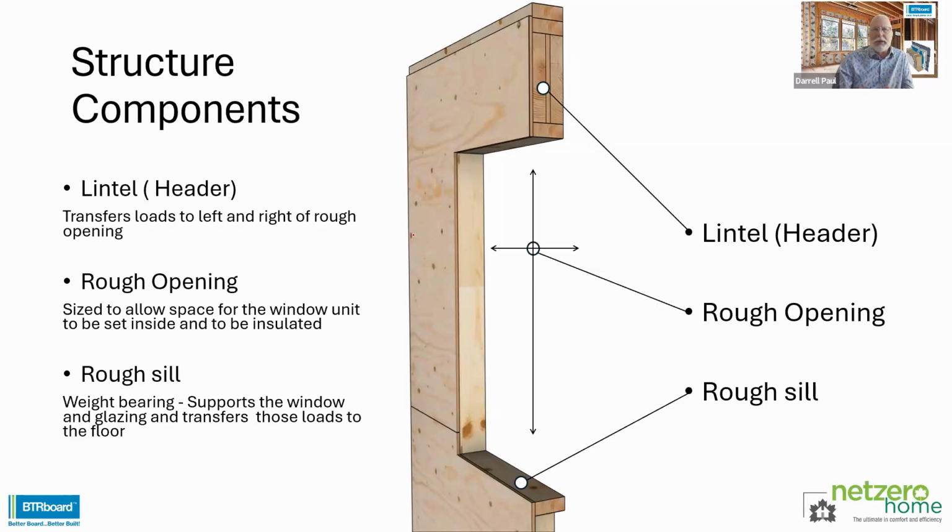All right, so there's some of the building science. We talked about the 4 control layers: water, air, vapor, and thermal. And we've talked a little bit about the first and second plane of protection, but let's go back to the rough opening. So here we're back to a rough opening. Maybe you've stripped the entire wall, maybe right down to the framing, or maybe this is what you need to envision as you're doing the construction, envisioning what's behind those walls.